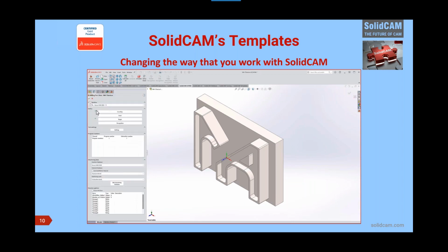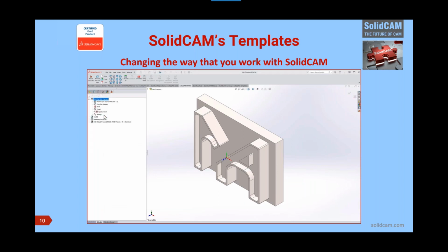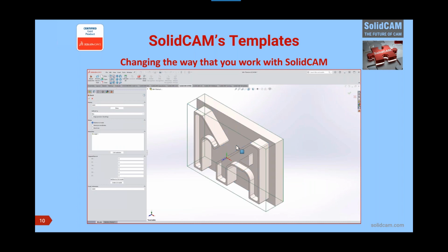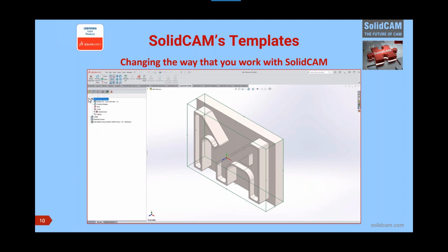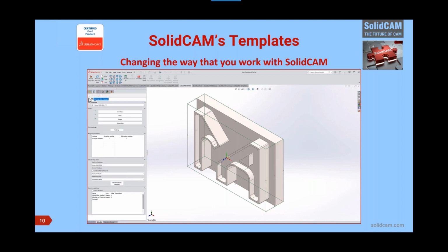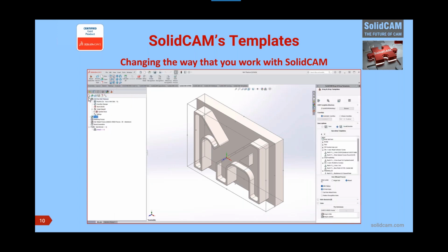And now we have an opportunity to set the stock up. So of course we'll identify the stock that we want to use. Important feature, by the way, when you're using iMachining especially, make sure your stock definition is correct, okay? It's going to help you a lot.